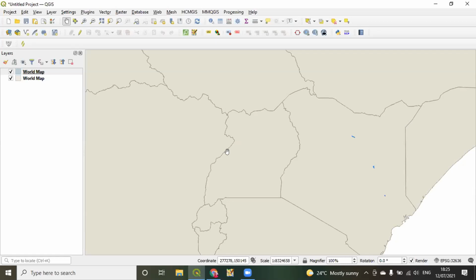Hello, this is Isaac. Thank you, Rehema, for the presentation, but I need clarification on the coordinate system. I've been using GIS and AutoCAD. Sorry, it's not part of the module. But for Uganda, I've been using ARC 1960 for a while. I don't know why you're seconding WGS UTM, but I still think ARC 1960 covers Uganda better. I can share its EPSG number and you try it and see the area it covers.